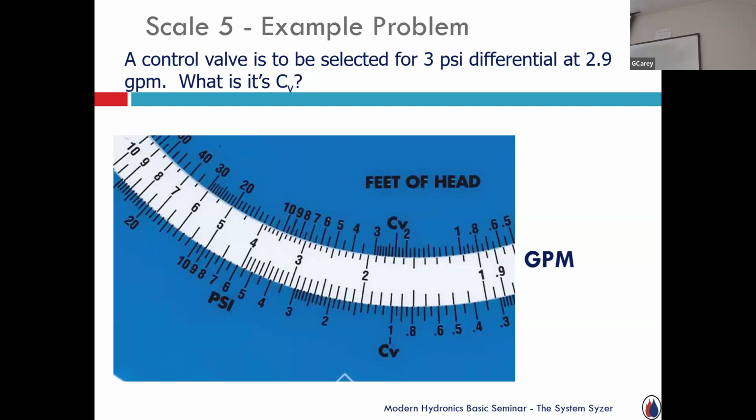The point being that a lot of times the output from water flow rate is very non-linear. You need a really high delta T, which means you've got to really reduce the flow to have a performance change downstream. So if I have this non-linear behavior, and then I introduce this really high pressure drop valve, as I stroke, I really throttle down on the flow rate, and that'll have an immediate impact on the output downstream, a much faster reaction, much more accurate.